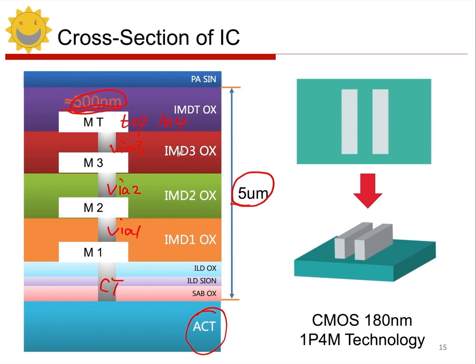In a 180 nanometer process, a metal line can be 180 nanometers wide, defined by the transistor's minimum gate length. The metal line's width is usually wider, like 220 nanometers, which seems thin but is 500 nanometers thick. After processing, these lines resemble walls with parasitic capacitance between them due to thickness.